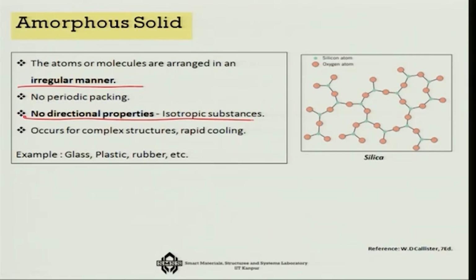One is that, as I told you, the cooling process can govern whether you get enough time for the liquid to change to solid phase such that the regular lattice formation is possible. So, with a very high cooling rate, you can even make metals as glass, and we call them metglass.